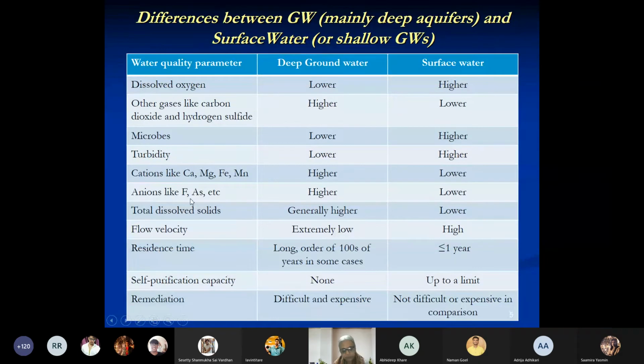They will precipitate because, let's say you bring deep groundwater to the surface. If the DO level is very low, close to zero, many of these compounds like iron and manganese will be in dissolved, reduced form, Fe2+ and Mn2+. You bring it to the surface, they come in contact with oxygen from the air and get oxidized.